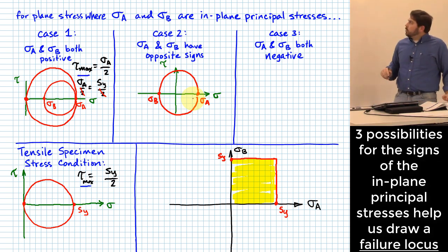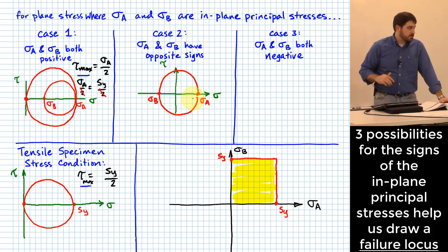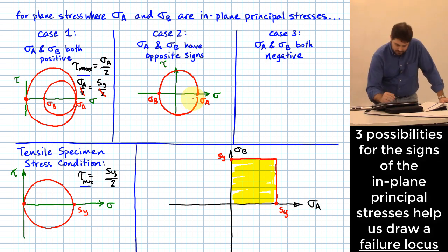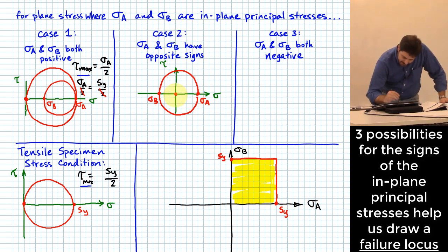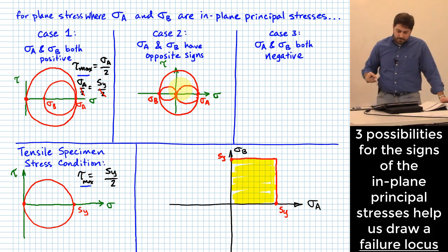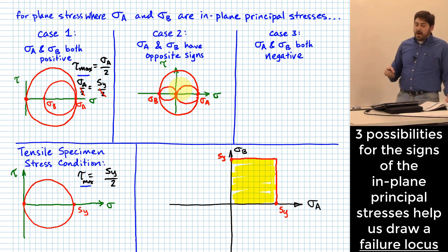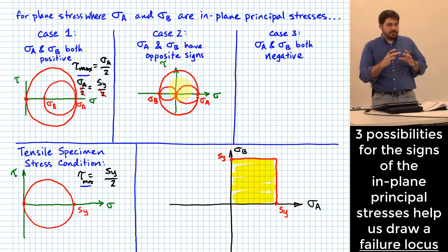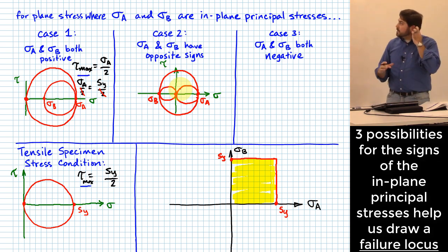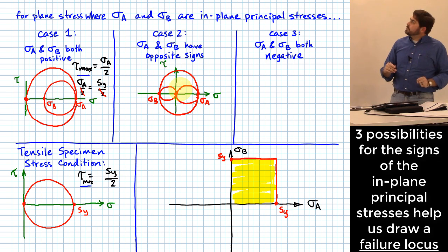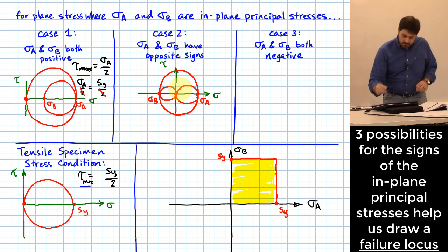Okay? And where's my other principal stress after I've taken care of my in-plane principal stresses? 0, again. Well, that just sets up a situation where I can look at either of those two other circles on Mohr's 3-circle diagram. Those do not have a bigger radius than the first circle I drew. Okay? And so what would we predict in terms of the maximum shearing stress in that case?